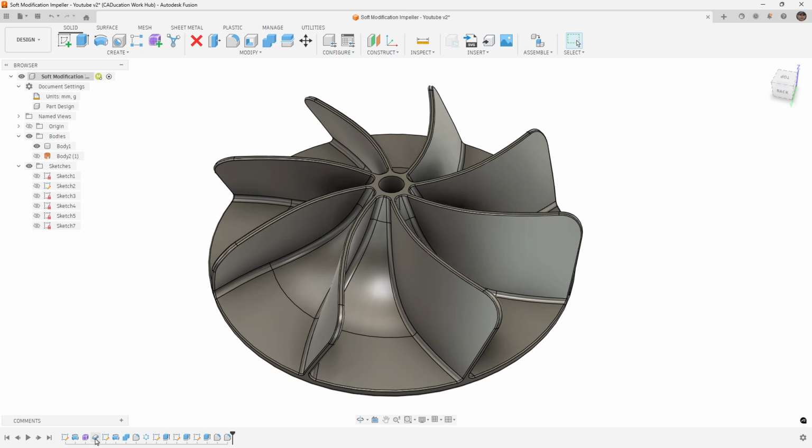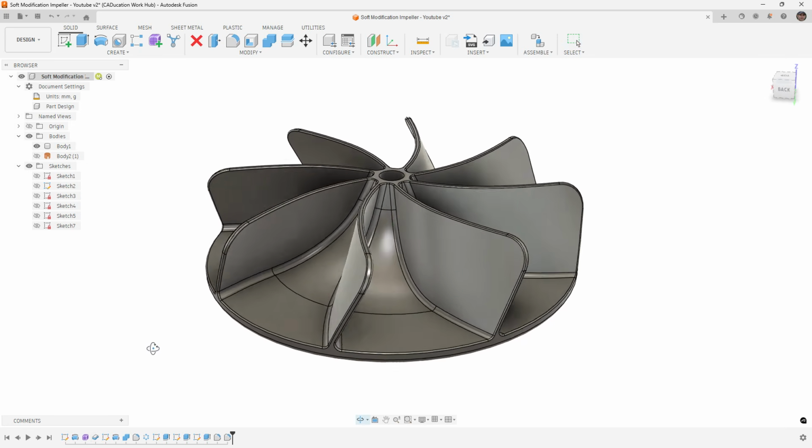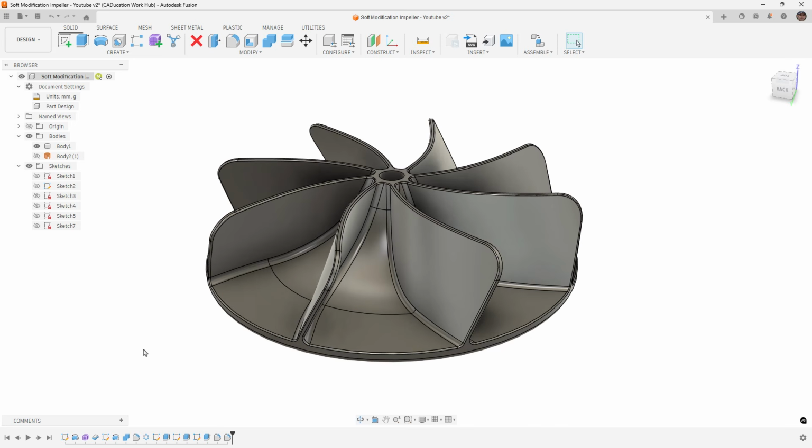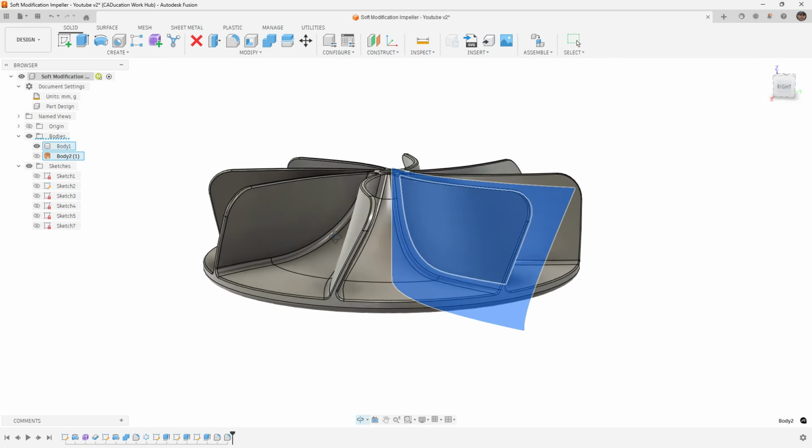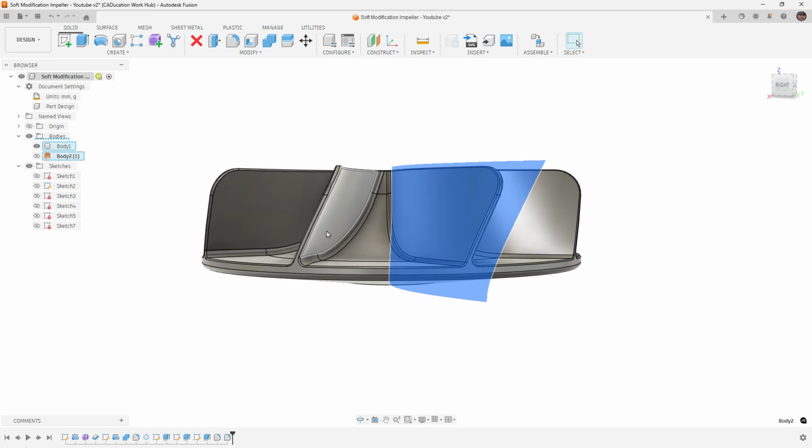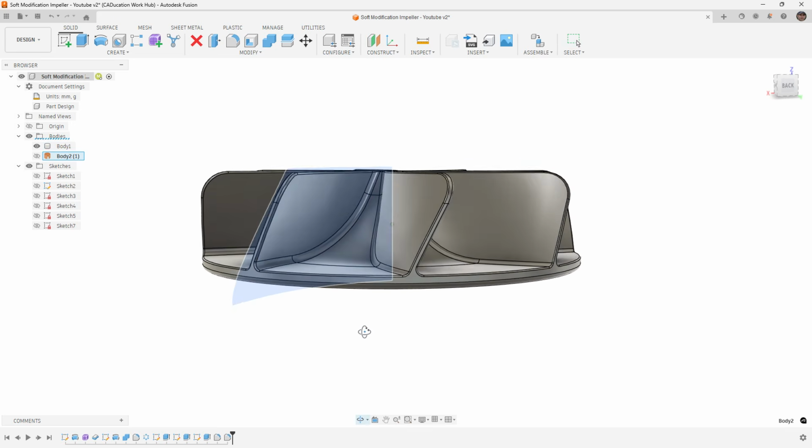And one of the main benefits here is because the freeform model is essentially converting to a surface. That surface is getting thickened, and then it's getting trimmed, and all the additional features are getting added to it. Fusion doesn't really care if we delete edges or extend edges, make it bigger or smaller, because at the end of the day, when you finish the form, it's converting back to that surface. And so as long as we don't go from, let's say, one surface to two, and then it's confused about which one to thicken, it will still allow us to go back to those simplified versions where we have reduced edges and we can play around with them a bit easier.